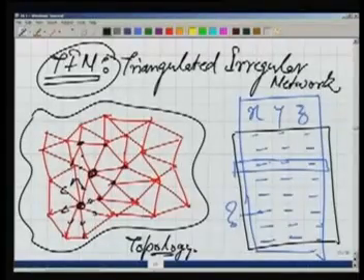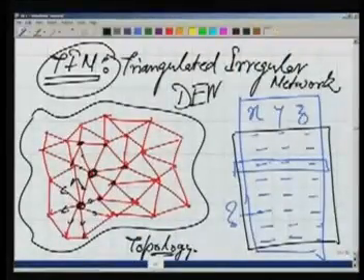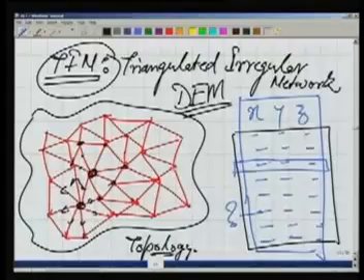Now the use of this is, if you are doing any work on this TIN, if I'm selecting a point, I know what is the next point to it, what all points are the neighbors for that point. So we know that relationship. So this is another way of creating a digital elevation model, of storing the data or the topography in the computer.